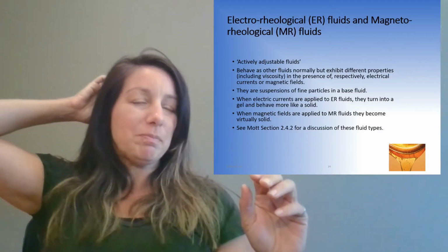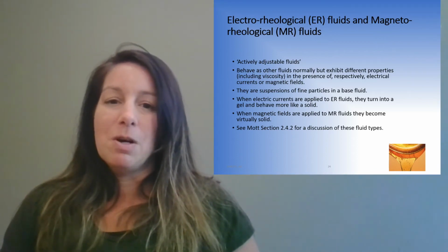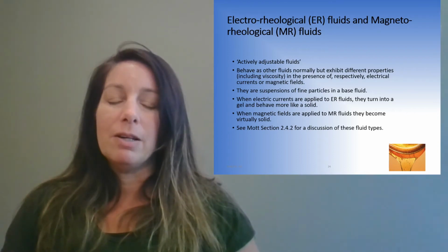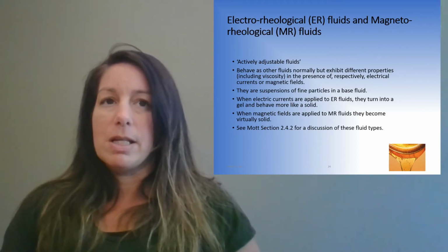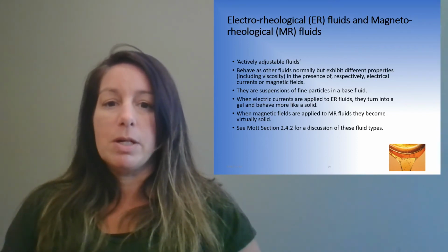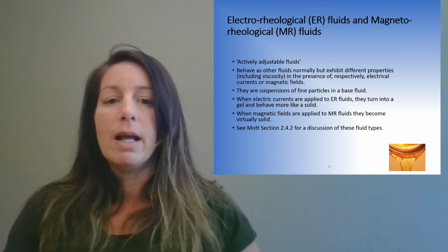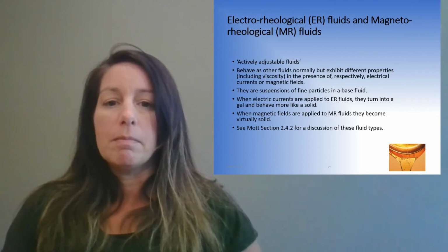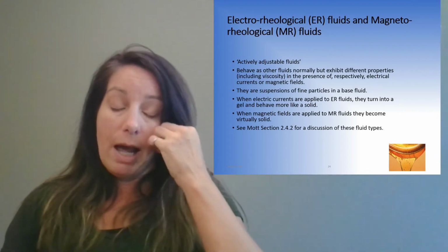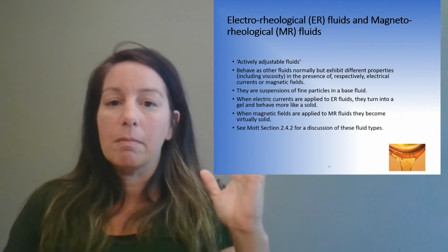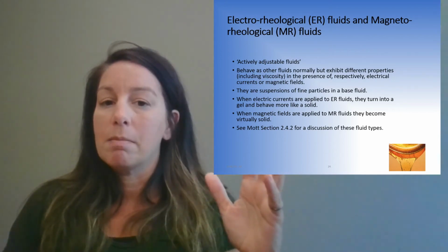I'm going to do my best to pronounce this. Electrorheological fluids and magnetorheological fluids, so ER and MR fluids. These are actively adjustable fluids. You can get it by their names. They behave as other fluids normally do, but they're a little different in their properties, including the viscosity we're talking about now, in the presence of, for ER, electrical currents, and for MR, magnetic fields.